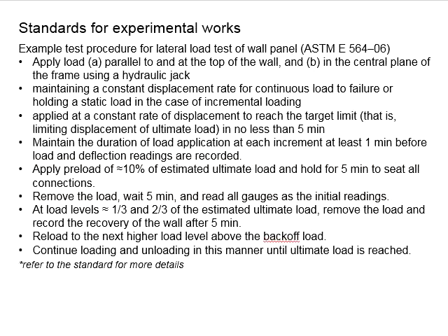Now you're going to start your testing. Based on the estimated ultimate load, you're going to increase your load to about 1/3 and 2/3 of the ultimate load, which you estimated earlier, and then remove the load and record the recovery of the wall after 5 minutes. That means there are 2 cycles of load here.